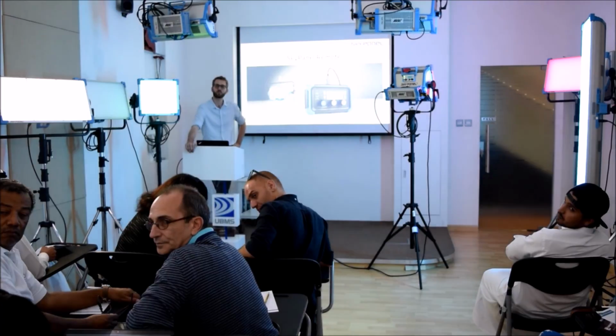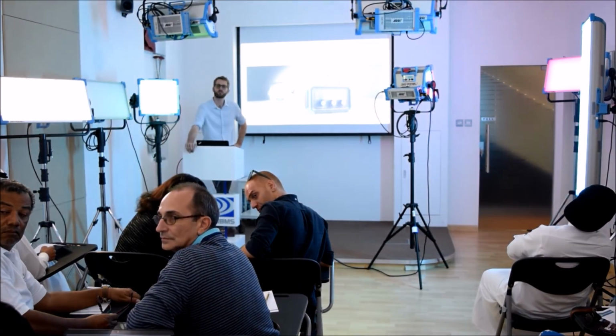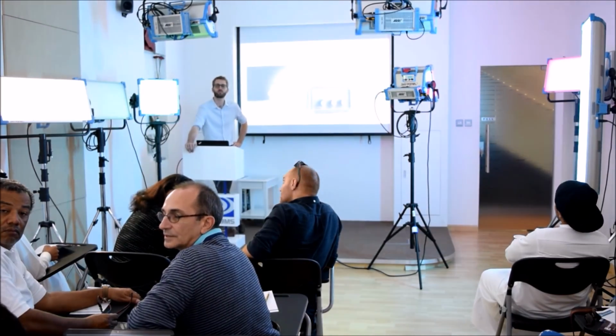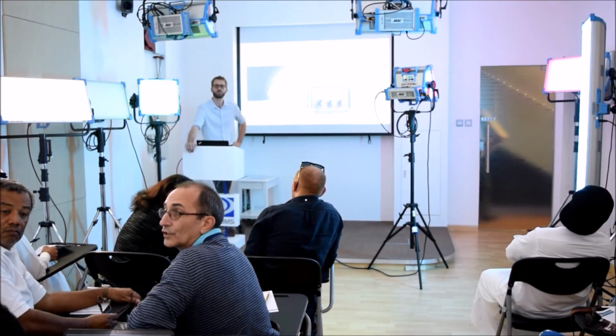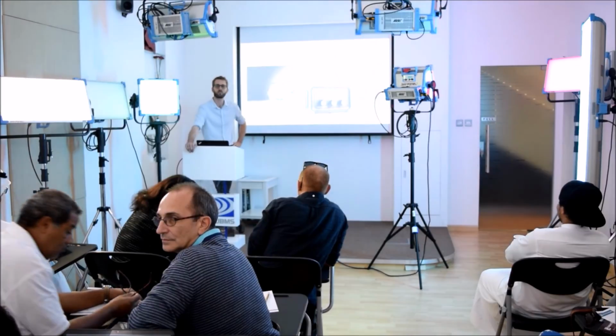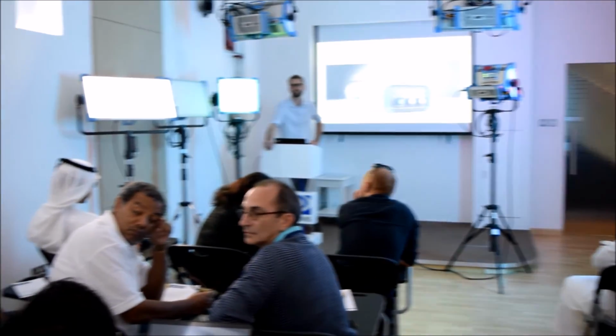It comes to the DMX splitter, and from DMX to the control desk is DMX, but the other is dedicated Ethernet. It has an IP address for each light, so in the interface you can see it's a red or a green, so you can easily find out.